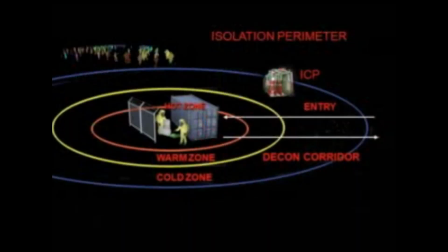Next, we need to establish hazard control zones and designate areas at a hazardous materials incident based upon safety and the degree of the hazard. This means the establishment of hot, warm, and cold zones. A hot zone is the control zone immediately surrounding a hazardous materials incident, which extends far enough to prevent adverse effects from releases reaching personnel outside of the zone. It may be oblong in shape, but should cover any area with known or suspected contamination or where foreseeable spread of the incident might occur.